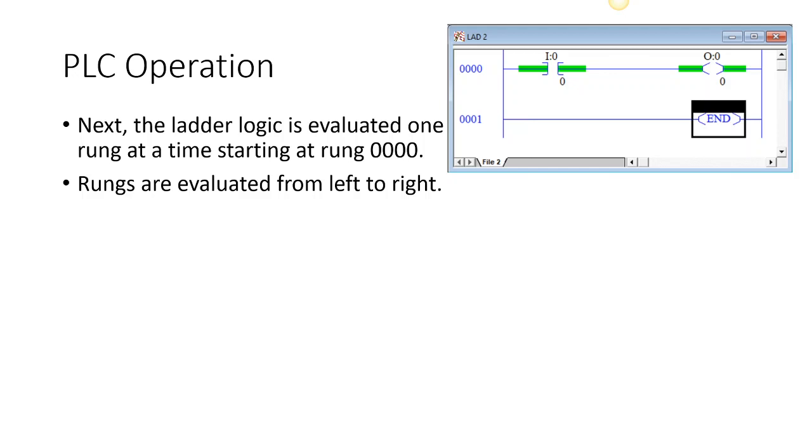The rung, we're gonna start at 0, rung 0. These numbers out to the left-hand side in the upper right-hand corner there are showing the rung number. And again, we're not starting at rung 1 like we did when we did our hand drawings for manual motor controls. Everything in the PLC is going to start counting at 0 and then go up.